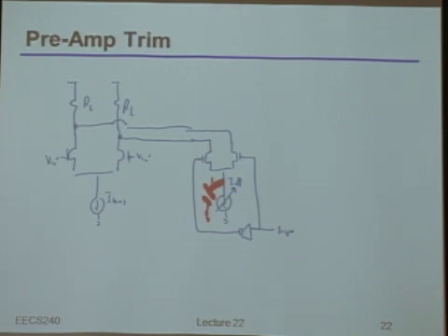Now, having said that, and you guys should do this calculation yourselves once, I promise you that the extra power you spend on doing this is way less than the power you would spend to just upsize this device. Because even though making the devices smaller makes their offset bigger, the amount of current you have to spend here in the first place is proportional to how big that load resistance was. So if you make the devices smaller, the load resistance gets bigger. Even though you need a wider range in the DAC, the net DC power you'd have to spend will go down. But having said that, indeed, that is one of the negatives of this topology, which is you have extra DC power consumption.